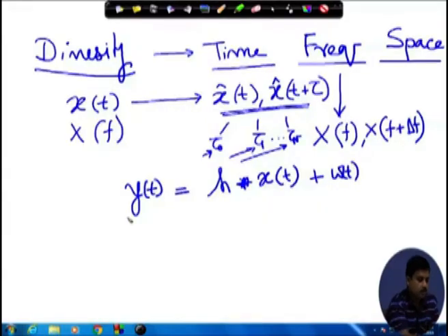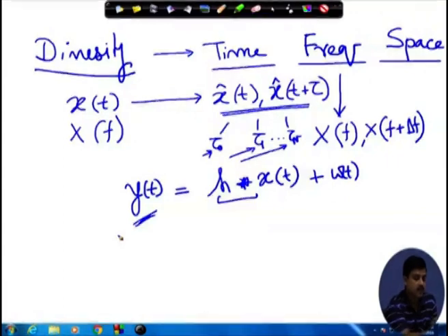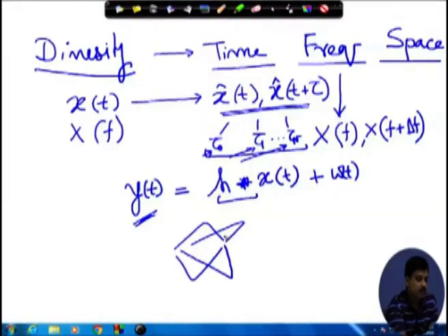So, I would be receiving multiple copies because of this convolution, and if these copies are uncorrelated, scattering, then I could take advantage of it and do certain things. There are methods of doing it. If it is flat fading, that means all these are at the same delay, then still you have multiple paths. The signal does come from multiple paths, but since the delays are the same, they would appear at the same time and we cannot separate them. They are appearing at the same instant of time.